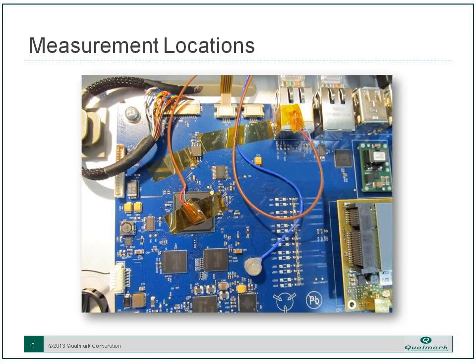The thermal and vibration responses vary significantly on different locations of a product, even within a few centimeters. You want to record specific locations of the thermocouples and accelerometers with descriptions and plenty of photos for your report. In HASS, the product configuration and fixturing will be different, so the measurements on the product in HASS will help you understand the effect of these differences. In order to make that comparison accurate, you have to have a good record of your measurement locations.